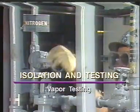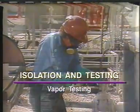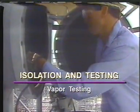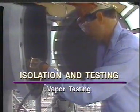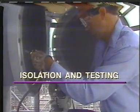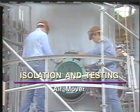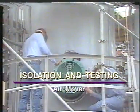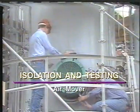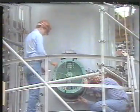Purging with inert gases and water flooding or flushing should remove all hydrocarbons from the tower. But we can't assume the tower is safe until it is actually tested. There are several different types of hydrocarbon detectors and analyzers that can detect the presence of hydrocarbons. Before anyone enters a tower, it must be tested with one of these devices. After the column is purged and tested for hydrocarbons, one of the manways is opened and an air mover is turned on. The air mover can be a fan or an air eductor like the one shown here. In the event that any hydrocarbon vapors are released during the cleaning of the tower, the air mover will sweep these vapors out of the tower.